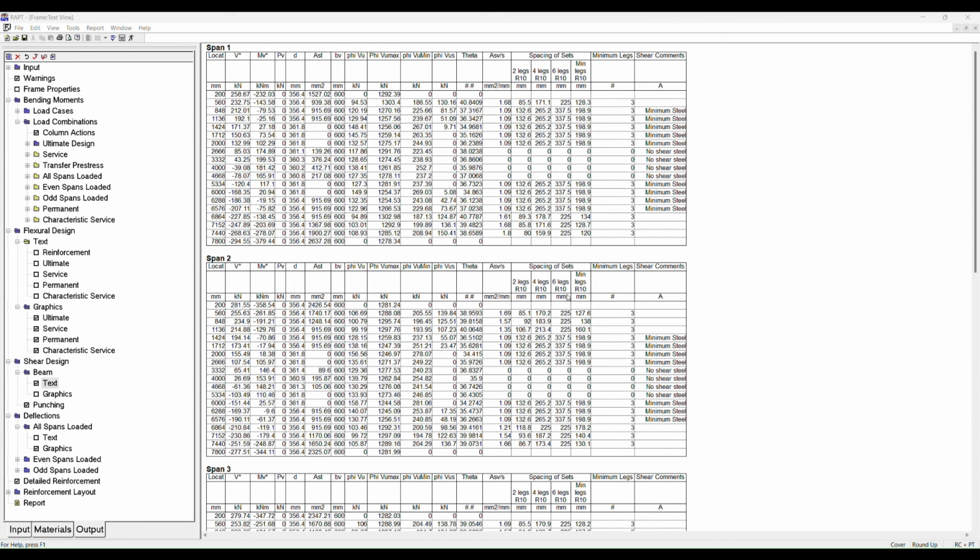Sometimes RAPT will add reinforcement if it is required for the shear offset rule. Sorry, in shear comments, this is just shear ties, so it's telling you that you need the minimum steel arrangements. Here you need no shear steel. For Eurocode, you will always need shear steel, even if you don't need the minimum amount required. You still need to put a nominal amount in.